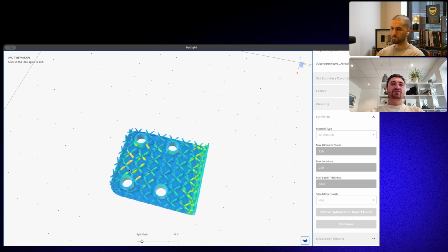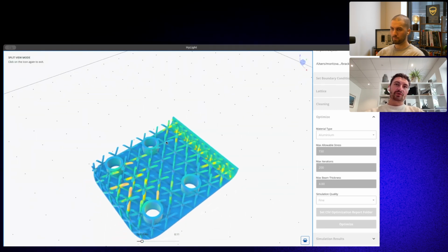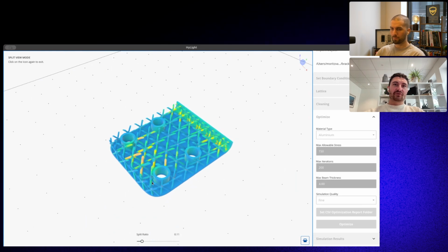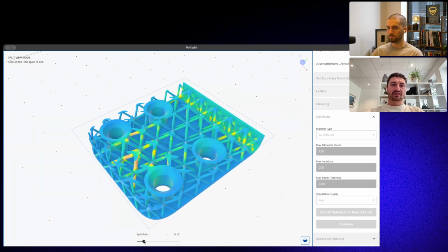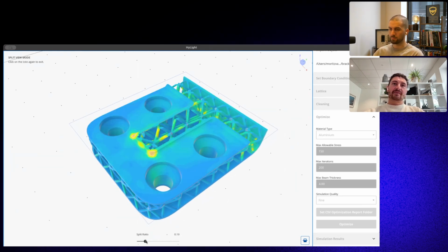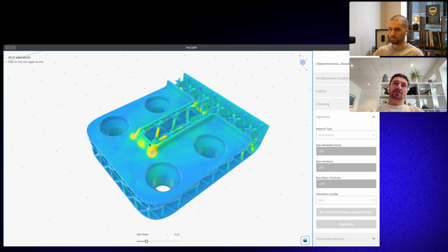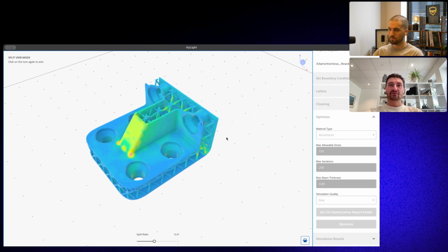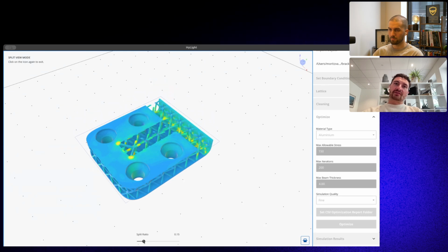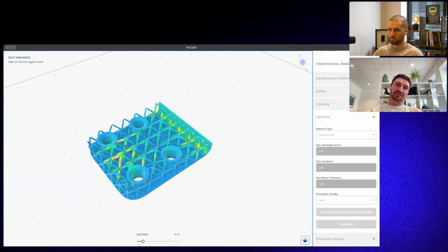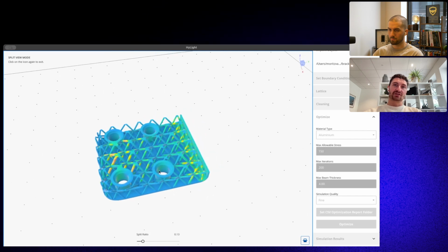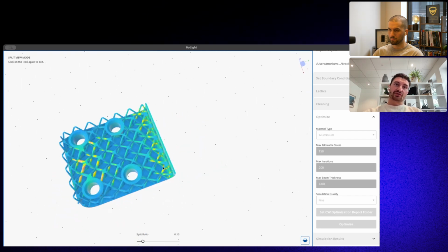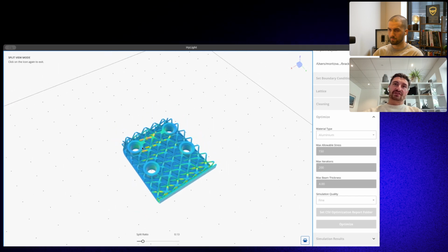As you can see, the lattice structure generally stays pretty much untouched, except for the regions, as we were already seeing before in the other bracket, the areas of highest tension, which are in this nosy structure here in the front. It's the same load case as before. So I'm pulling effectively on this side and I fix the bottom. And due to that loading condition, of course, there will be tension in this region here. Let me turn this so it's nicer to see.